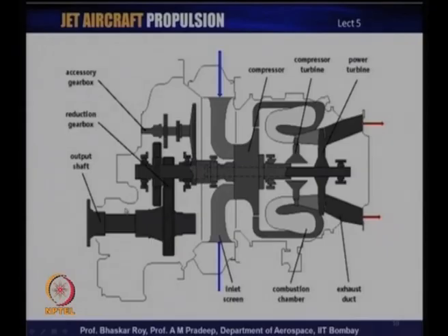which runs the rotor, and then you have the huge reducing gearbox, which reduces the rotating speed by a factor of 50 to 100. And these are the systems which you have, and this is the inlet. So, you have a sidewise inlet of air going into the basic engine, and quite often the exhaust also could be something like this, sideways.